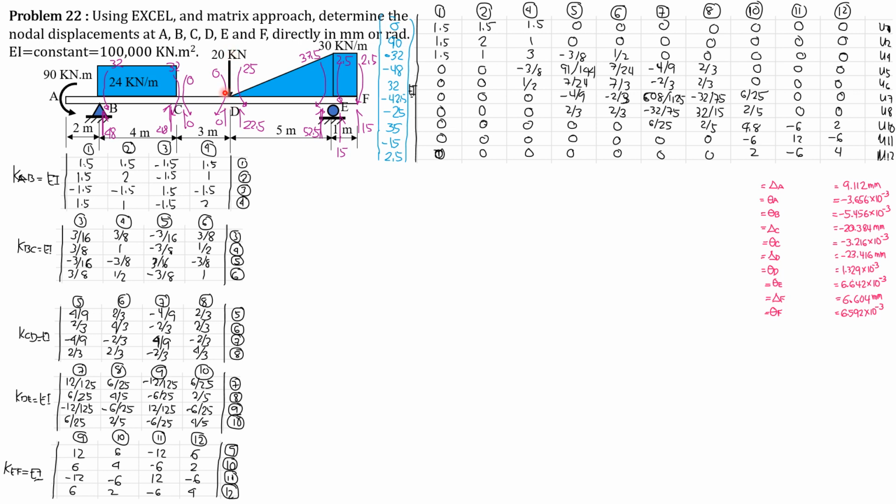But it is a load that is downward combined with the triangular load, because at the left it's 0, at the right this value here. But before we solve this value, fixed moment here is WL square over 30. So 30 times 5 square over 30 is 25 kilonewton meter counterclockwise as shown. While here WL square over 20, so 37.5 kilonewton meter clockwise.